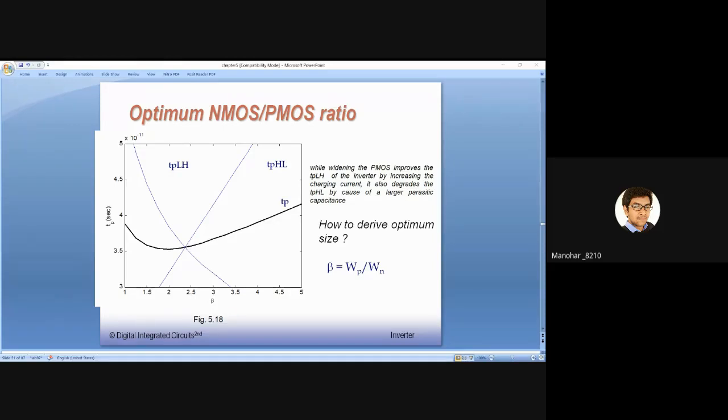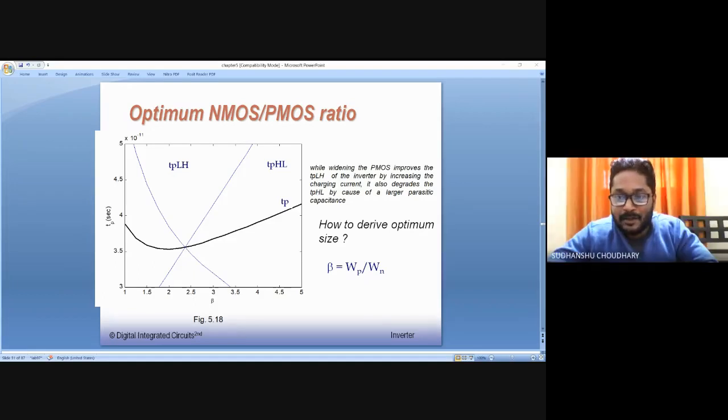Why does it happen? Earlier the VTC is similar to the ideal case, and then it is not. Why? Yeah, so there has to be some limit. I mean, you are operating in the sub-threshold region. In the sub-threshold region there is some limit, after that the gain of the circuit starts falling down, right? So there is some limit.